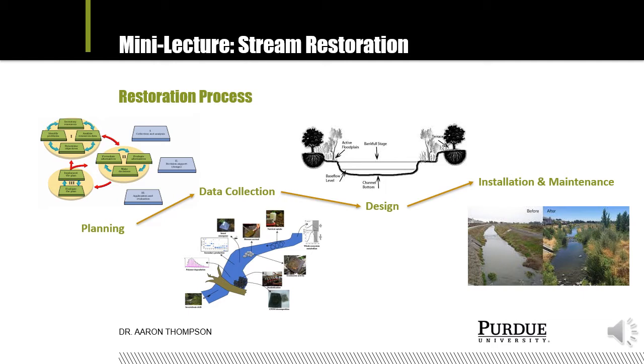The greater the amount of impervious surface within the watershed draining to that stream, the faster that stream is going to flash during peak flow periods, and the more armoring you're going to have to do. These are all factors when you think about the development of it. Before I leave this slide, though, remember that the installation and maintenance could also be a years-long process.